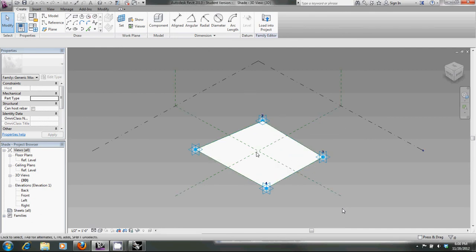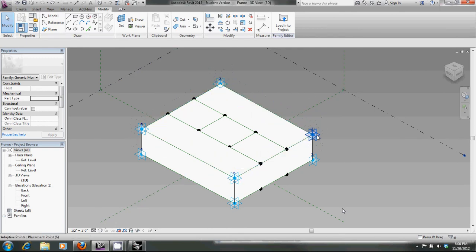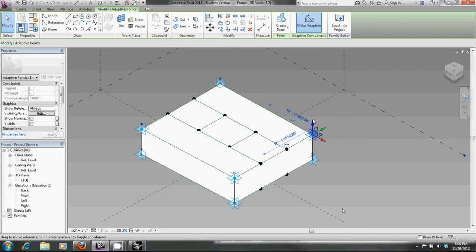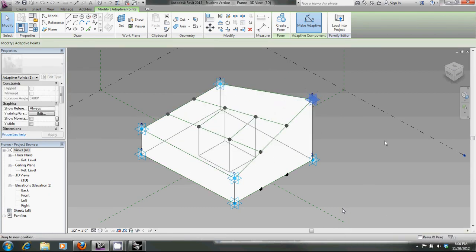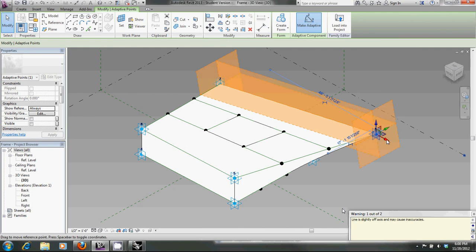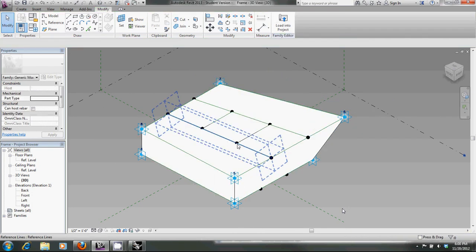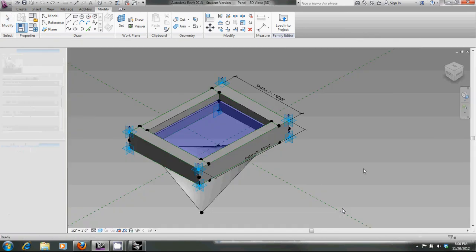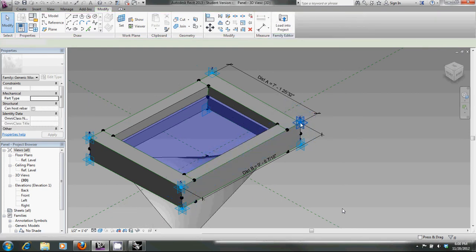So what we've done here is just basically build a quick adaptive panel to adhere to those points, and this is just really a quick and dirty, this one's an 8-point adaptive with an oculus in the middle, but as you can see we're flexing this thing all around, and it's totally adaptive, and all of these numbered points are going to adapt to the numbered points that come in from Rhino. And again, this is just a different type of panel that we created.